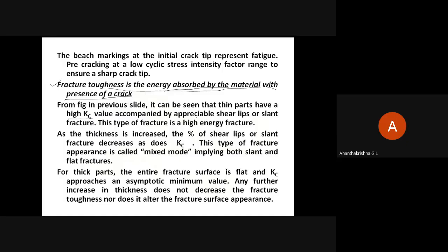Accompanied by appreciable shear lips or slant fracture. So this type of fracture is a high energy fracture. Next, as the thickness is increased, the percentage of shear lips or slant fracture decreases, as does the critical stress intensity factor. Okay, this type is called mixed mode.